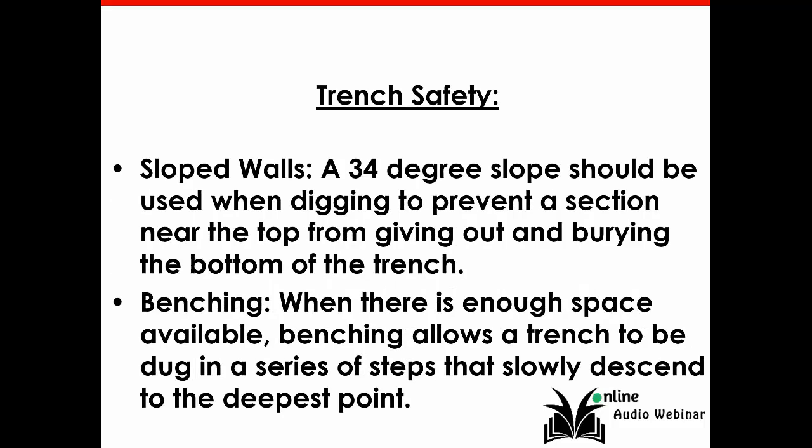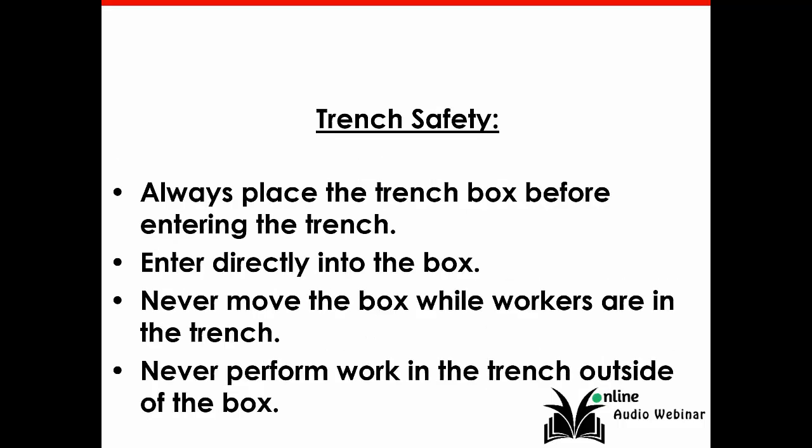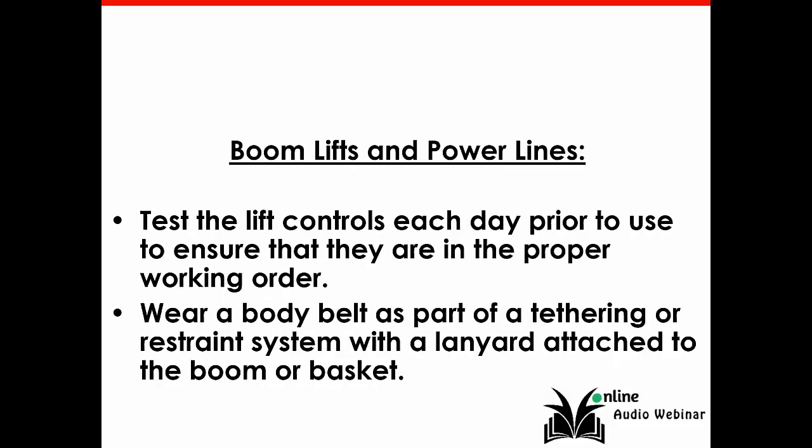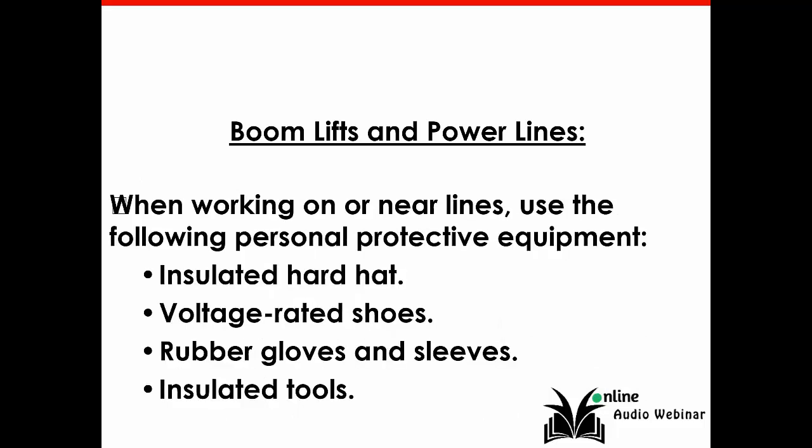So sloped walls, benching, and you want to construct a support system made with posts, beams, shores, planking, and hydraulic jacks. Now for trench safety, again, we're touching some of the highlights. So boom lifts and power lines. Do not exceed the boom and basket load limits set by the manufacturer. So when working on or near lines, use the following PPE or personal protective equipment at a minimum.